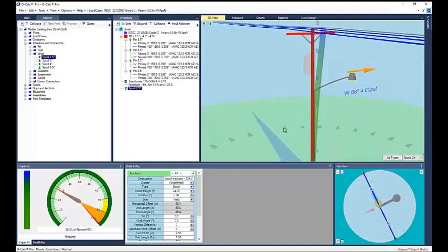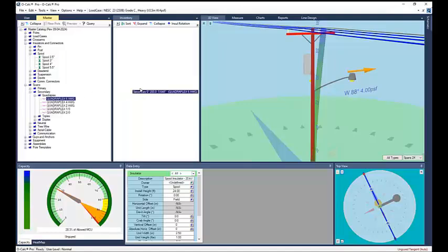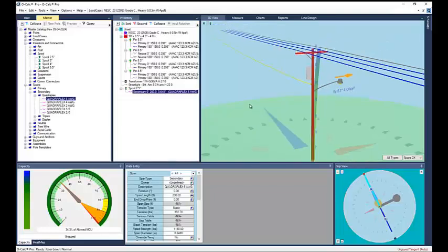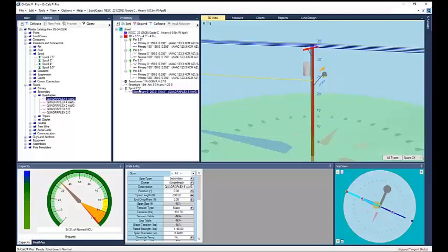So once I have it here, I'm able to add my conductor, and in the spans folder, we do offer some secondaries here in the folder, and I can choose from a quadruplex, triplex, or duplex. As I drag and drop to the spool, O-Calc adds that conductor for me in the opposite direction at 200 feet long. I can always change that.